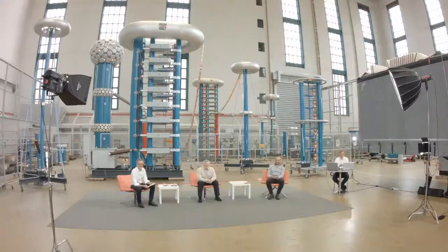I would like to add something, if I'm allowed to, 30 seconds. Acoustic sensitivity is much lower than electric, so we usually use averaging triggered on electrical signals. That is the proper method. The problem is if we do not have a stable trigger on one defect source, then it becomes more difficult. I think we will see in the near future better solutions to average on single defects and to get better acoustic sensitivity for localization. Was it shorter than 30? It was 24 seconds. Okay, excellent.